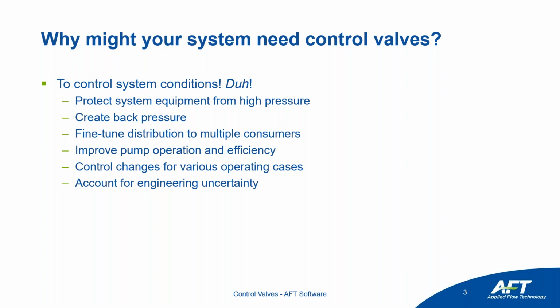Very often you'll see control valves downstream of a pump. So instead of applying a variable frequency drive to a pump and controlling how much energy you're adding, typically you can throttle that with a flow control valve instead. In some cases, whether or not that improves your pump operation depends on your starting point or your initial sizing process, but that is one methodology of changing where that pump's operating point is. Various operating cases, we'll touch on that in a little bit today. That's one thing that we could evaluate. Again, is our control valve going to be suitable for a range of operating cases it would have to run in? And then the final thing is using it to account for engineering uncertainty.